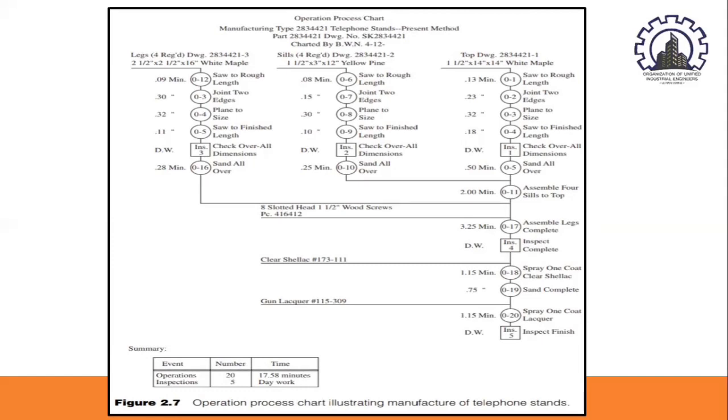So if you're studying an operation, employing an operation process chart, and the operator under observation is doing something on that particular product, then that is an operation. But if that operator inspects the quality or the standard of that particular product, then you will be using the square. Okay, so the sample completed operation process chart helps the analyst visualize the present method with all its details